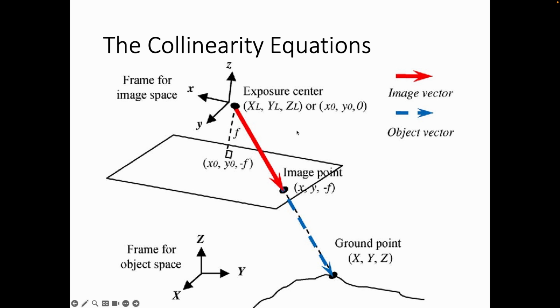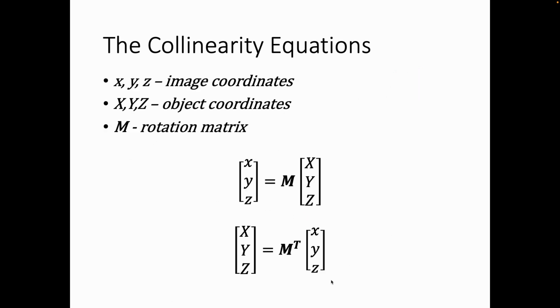And then we're going to need to know essentially three orientations, or three angles. So if we can get this vector identified in terms of its x component, y component, and z component, then we can identify the location of the ground point. And we won't be able to do this with a single vector, but by having multiple images that all have vectors pointing to this particular ground point, we'll be able to solve for that system. So let me show some math.